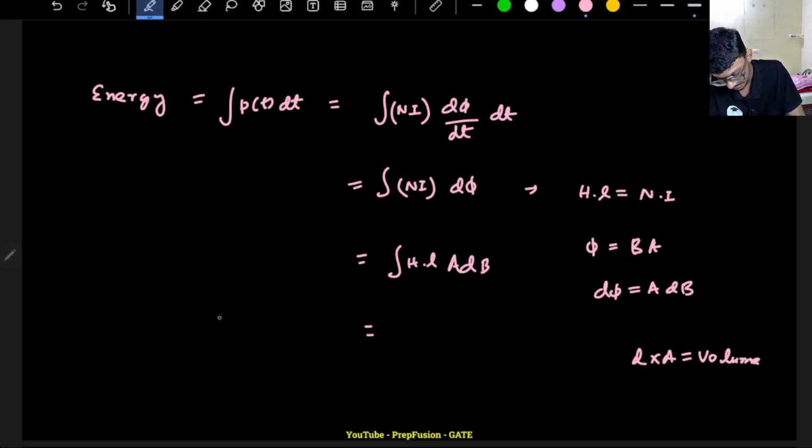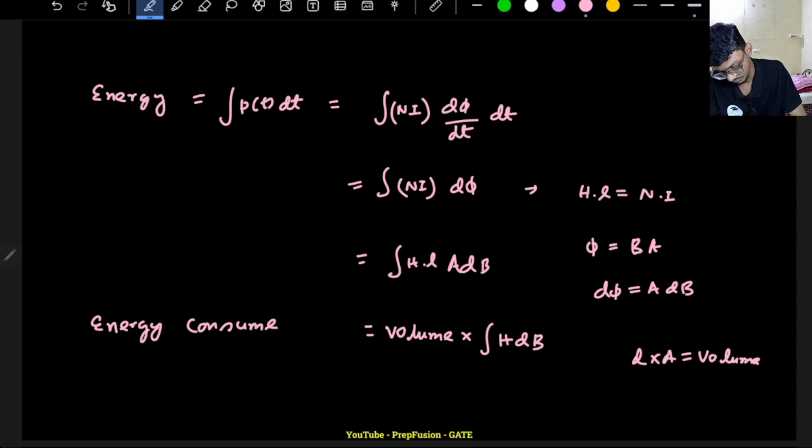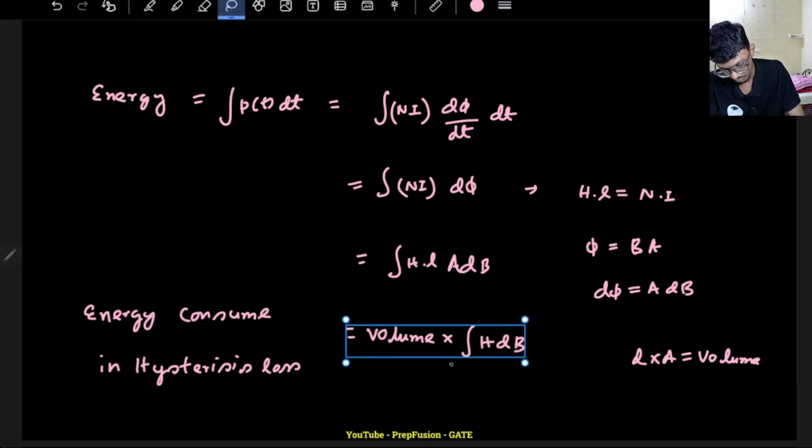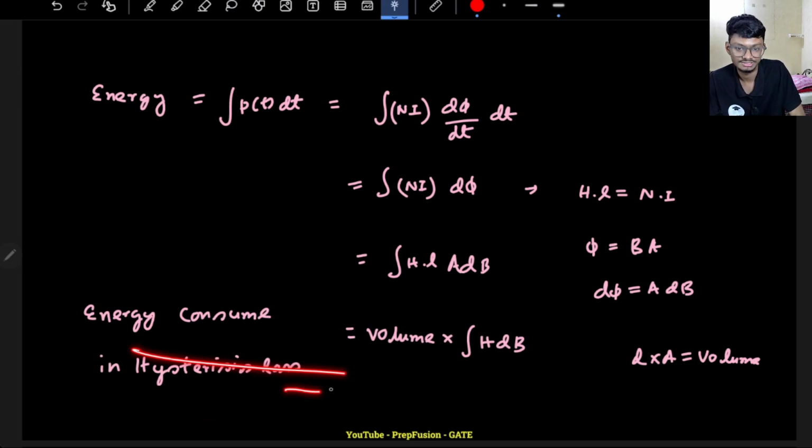So the energy that is consumed from the hysteresis loss is volume into the integration of H dB. So this is the energy consumed in hysteresis loss.